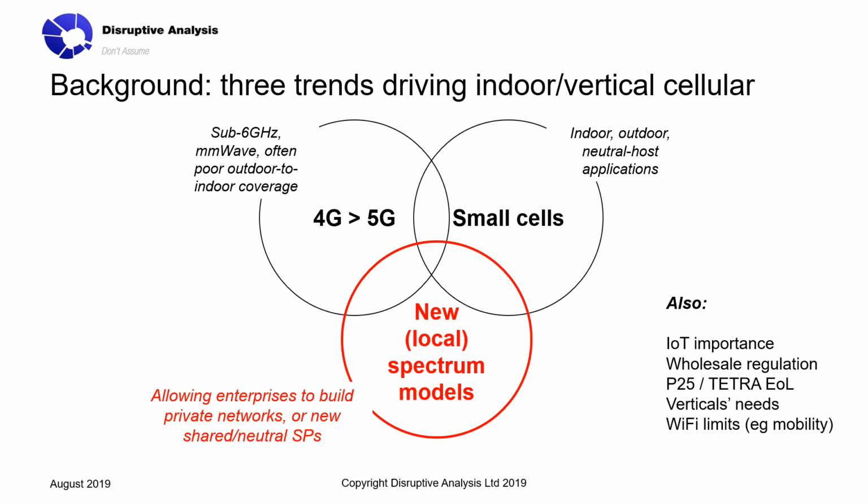Another aspect that we're seeing changing is a shift over time from distributed antenna solutions to ones that are more active and driven either wholly or partly by small cells for cellular, and that brings a set of opportunities and challenges. It increases the potential capacity for cellular coverage in buildings, but it also makes it difficult in that we start having to think about backhaul and deeper fiber in buildings. And the other question is whether you have one small cell which covers multiple carrier networks and any private use cases, or whether we need to have multiple small cells on one enterprise network.